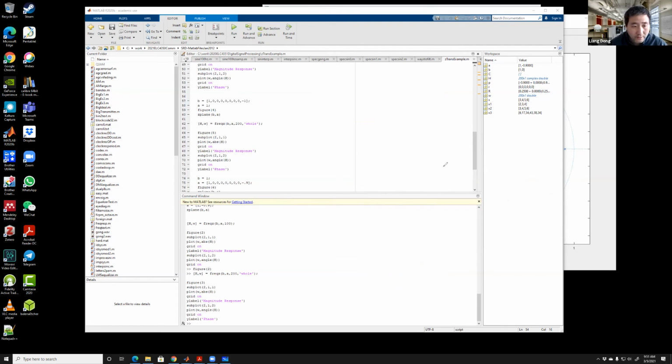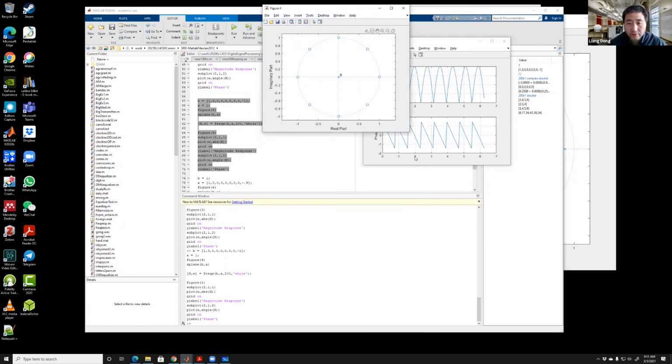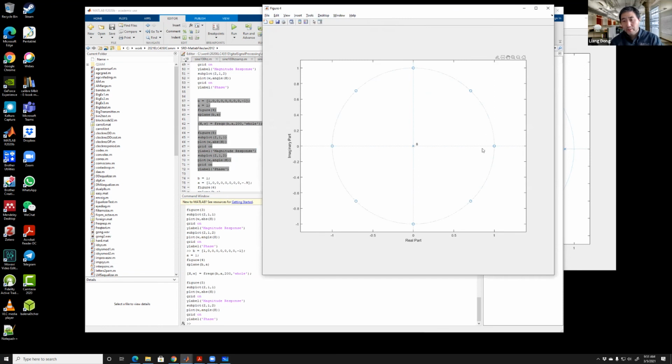From my plot, what we have here is figure 4 first, and figure 5. Figure 4 is showing the Z-plane. So indeed, it's showing me 8 poles at the origin implied, and I have 8 zeros on the unit circle. Now we care about these because when I have a real system, I really travel along the unit circle. So it affects me. Those are the 8 zeros.